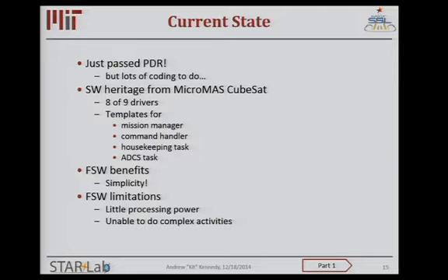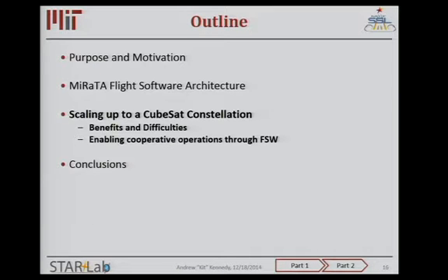But some of the limitations here are little processing power with the PIC-24, and that we're unable to do complex activities because of that processing power. And that's a direction that we want to head in the future, actually using a more capable processor and putting a Linux distribution of some sort on board. So that was my coverage of the flight software architecture for MiRaTA.